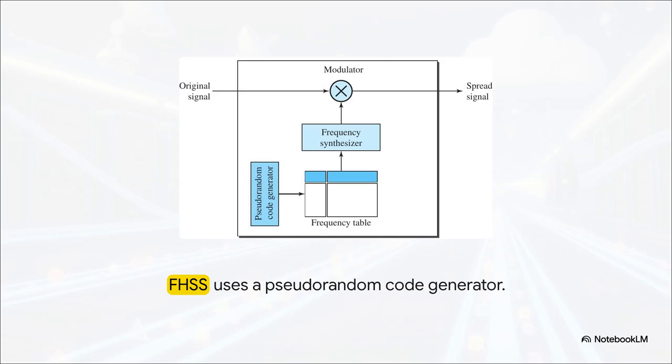One really clever way we achieve this is through frequency hopping spread spectrum, or FHSS. Instead of transmitting on one predictable carrier frequency that anyone could listen to, a pseudo-random noise generator forces the source signal to constantly hop between dozens of different carrier frequencies many, many times a second. It's literally an elaborate game of whack-a-mole. If an adversary tries to intercept the data or a jammer tries to block the transmission on one frequency, it doesn't matter. The signal has already hopped to another frequency. Only the authorized receiver with the exact same pseudo-random sequence can reassemble those chaotic hops back into a coherent message.